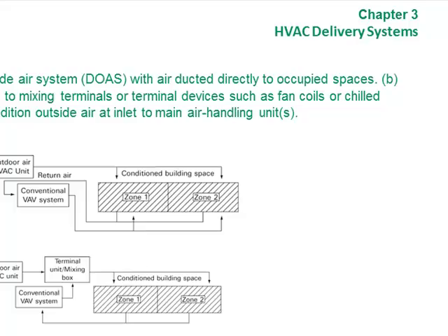How do you prevent high humidity? What takes the humidity out of the air? Cooling it down? Heating it up. Raising the temperature. So what kind of delivery system would do that? A reheating system, that's right. So an HVAC system which cools air and then reheats it is the best for that. Does that make sense? Okay.